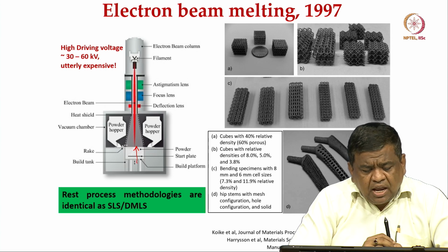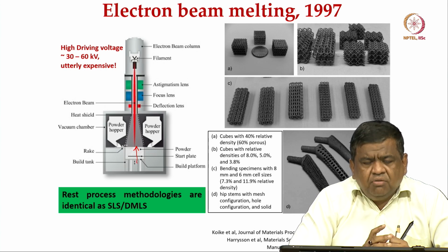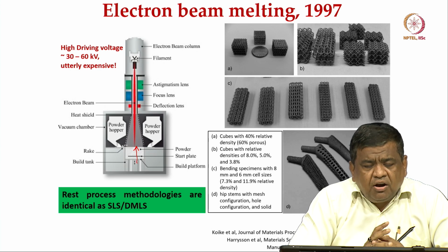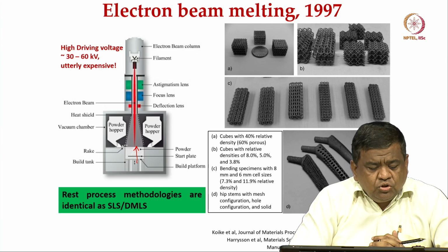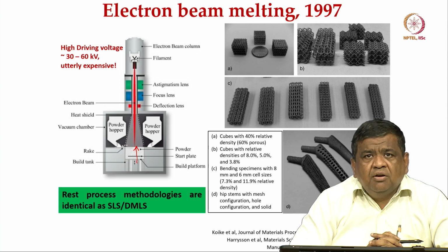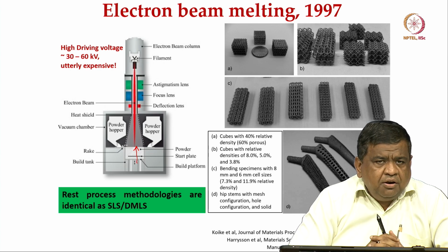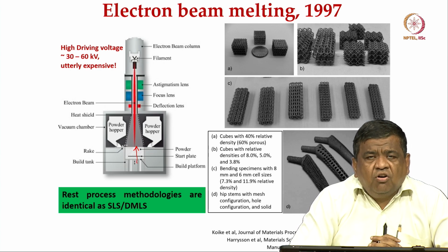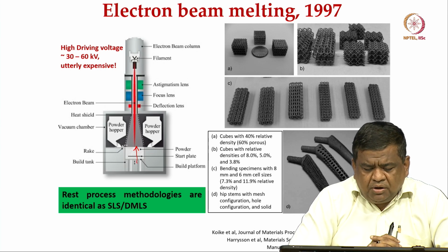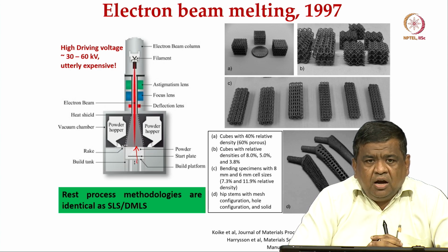Now, in terms of the capability and functionality of these materials, this manufacturing process is similar to SLS or DMLS or other powder bed fusion processes, or directed energy deposition, because here the major energy source is not a laser but an electron beam.